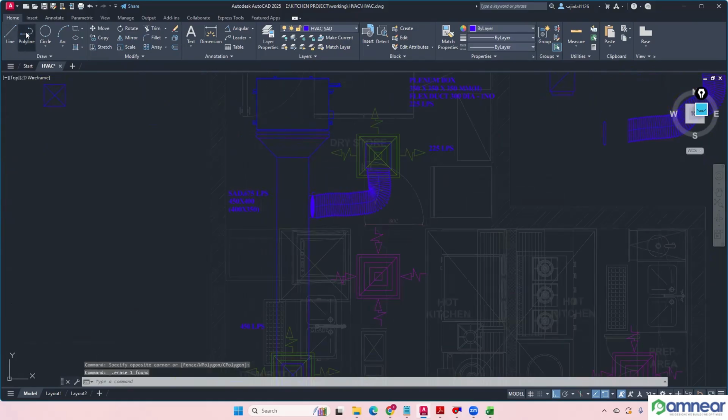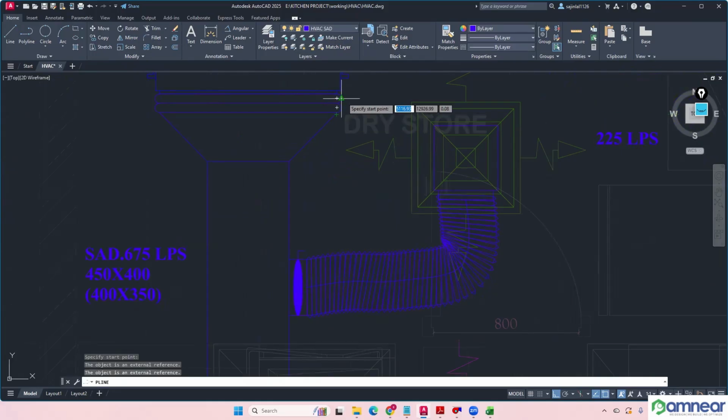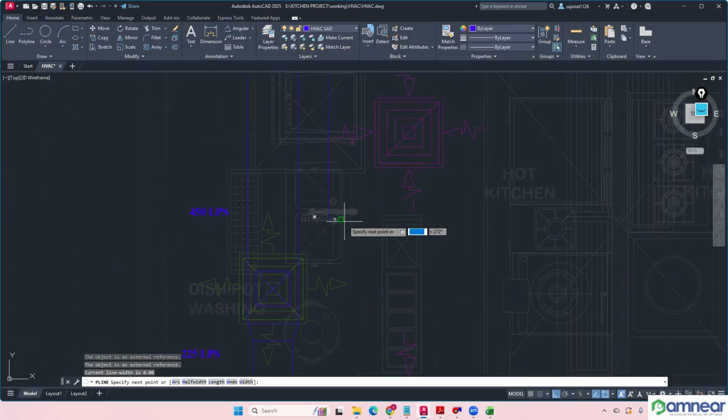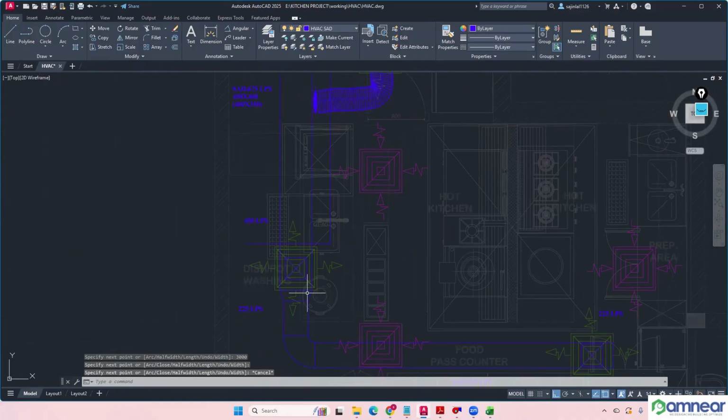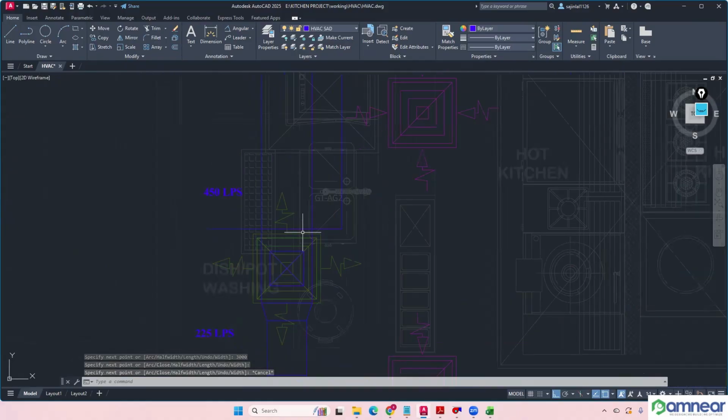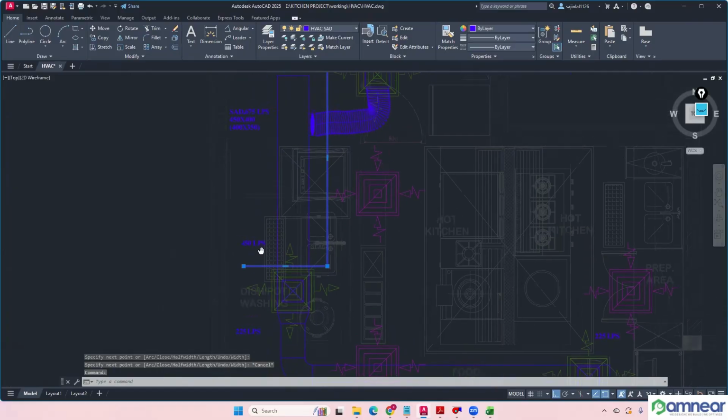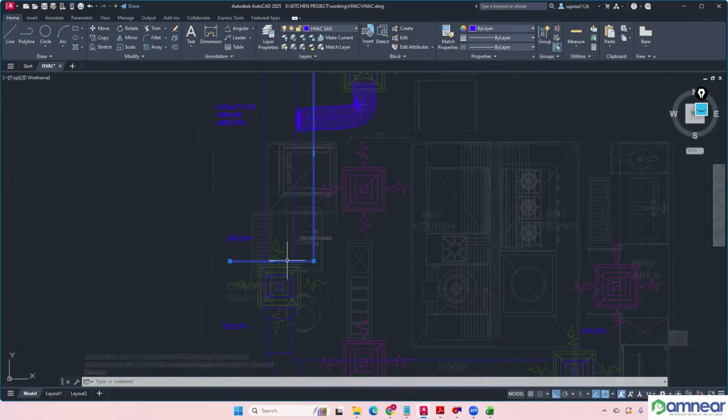For the first 3 meters we have to propose acoustic lining, from the starting of the machine to 3 meters. So up to here I need to provide acoustic lining. But if you are proposing it throughout the entire length, there is a problem. 3 meters only, that is fine.